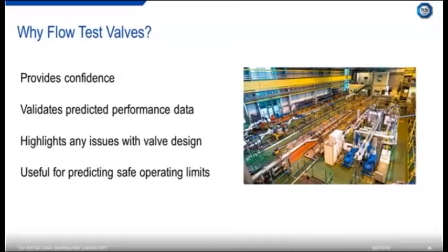Some of you might be thinking, why bother testing valves? If a manufacturer's giving me CV data, is there any point in actually doing it? Well, flow testing provides the end user confidence that the valve they've selected is going to meet its intended duty. A lot of the time we'll test a valve, and it will tie up quite well with the manufacturer's performance data, but other times we've tested valves and there's been quite a significant difference between what the manufacturer's claiming and what we actually see during a test.